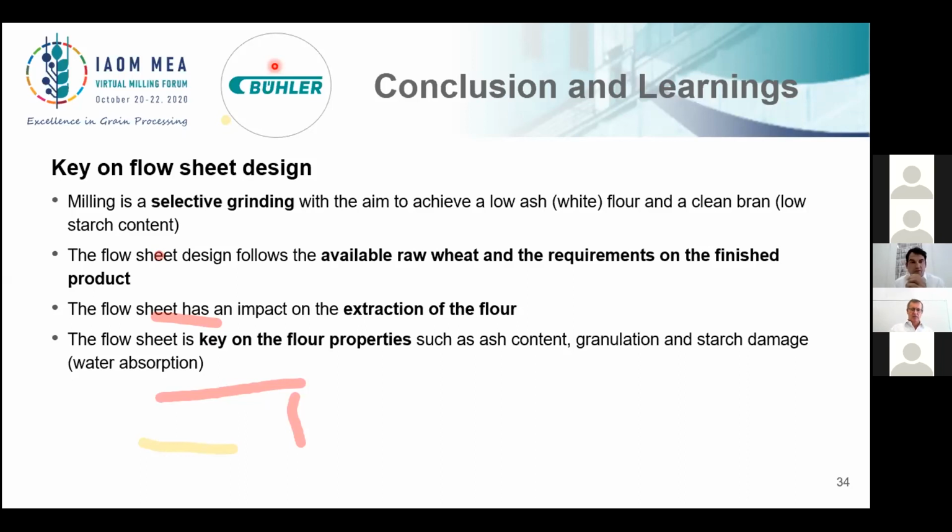The mill, of course, needs to take then the semolina. If we have sharp, the semolina amount will be higher, and the starch, let's say the bran particles, will be higher. So it needs more purifiers to purify if you have sharp on the breaks. So the conclusion is first break, second break, it's dull. Third break can be either or, and the fourth and fifth break usually are sharp.